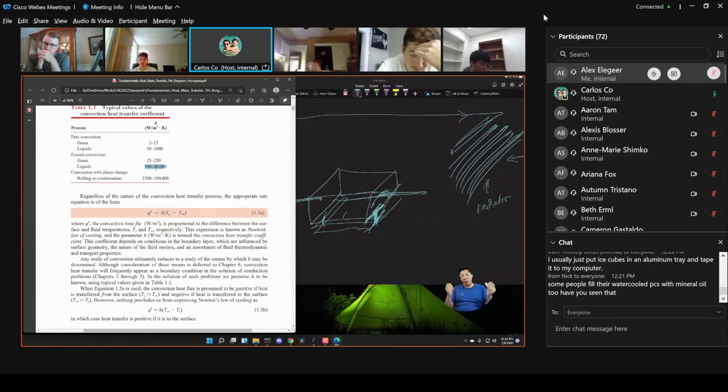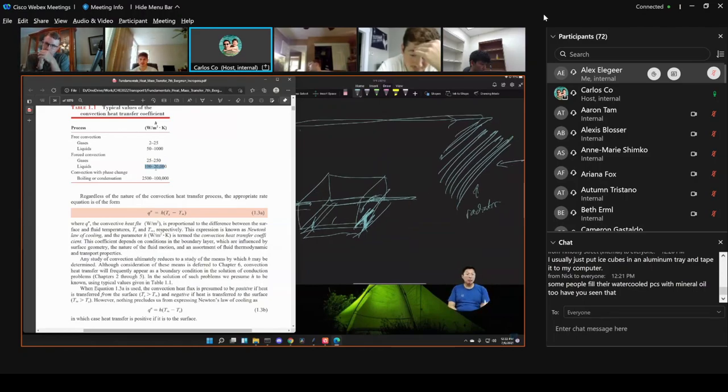But once you carry that liquid out, let's say to the back of your case, where usually you'll have a radiator, exactly the same as a car radiator, where the coolant passes through with a lot of surface area, then you can blow air through that, and you're no longer constrained by the tight volume right above a chip. This radiator could be as big as you want it to be. There's no limitation at that point, right?